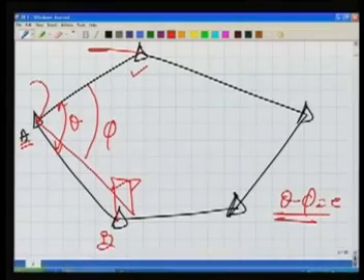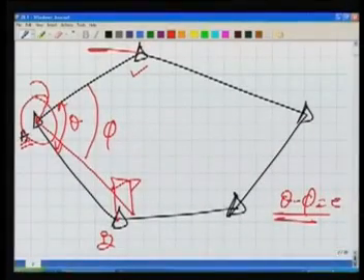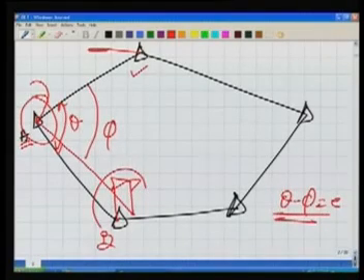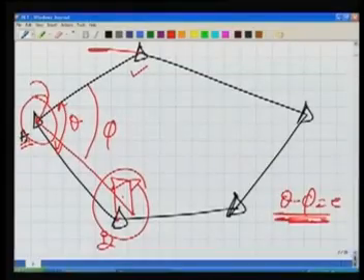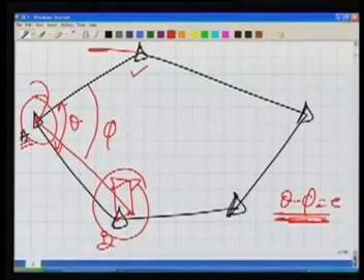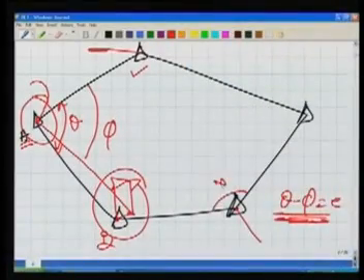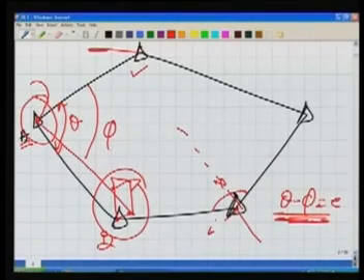So this miscentering of even the ranging rod, I am saying ranging rod in this case, it could be any target. In case of the total station, we use the target, so it could be the target. So if there is miscentering either of the theodolite or total station or of the target or ranging rod, there will be problem and we will have the error. Now we have to see the consequences of this error. What will happen? How will this error vary? What will happen if the length of lines of sight is short or long? What will happen if this error of miscentering is small or large? Also its direction. In which direction is this miscentering? Is it in the direction of the bifurcation of this angle, or is it in some other direction? Because in the direction of the bifurcation, the effect of this is maximum.